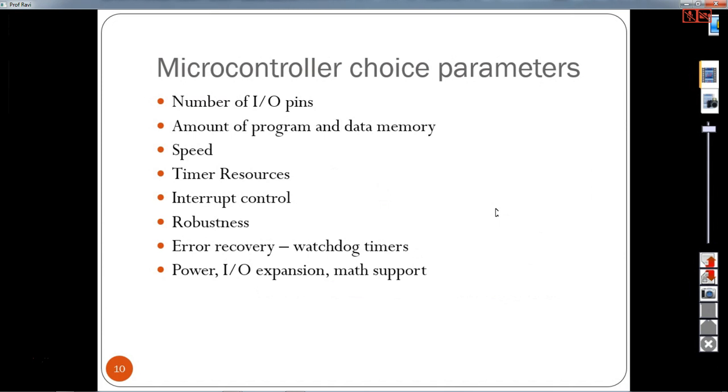The advantage is that the multiplexing concept which we used in 8051, in which port 0 can act as port 0, or address, or carrying data, three functions done by the same port, is not needed. Here you have separate address and data so that the speed of the microcontroller will be very fast.